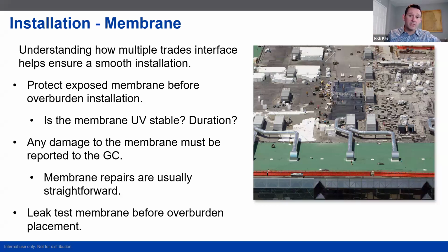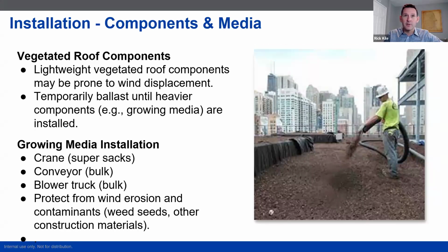Is the membrane being protected? Where are materials being staged? I always like to tell contractors, especially landscape contractors, if you damage a membrane, it's not the end of the world. It's the end of the world if you damage a membrane and then you cover it up because you didn't tell anybody. Then it becomes a significant issue. So making sure that everybody's on the same page there.